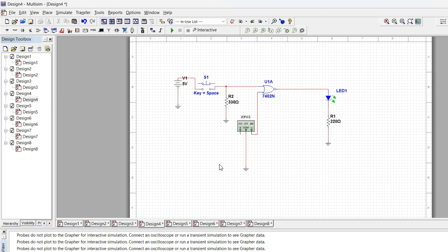And I think it's also a current limiting resistor for the logic gate input. So if we want the LED to turn on, it means we want the output to be 1. So for the NOR gate, we want the output to be 1, so we need both inputs to be 0 and 0.